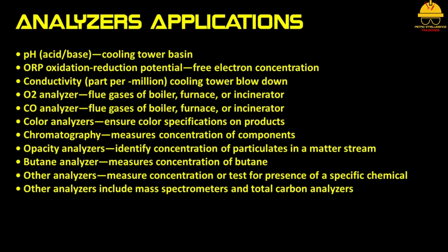CO analyzer is used for flue gases of boiler, furnace, or incinerator. Color analyzers are used to ensure color specifications on products. Chromatography is used to measure concentration of components. Opacity analyzers are used to identify concentration of particulates in a matter stream. Butane analyzer is used to measure concentration of butane.